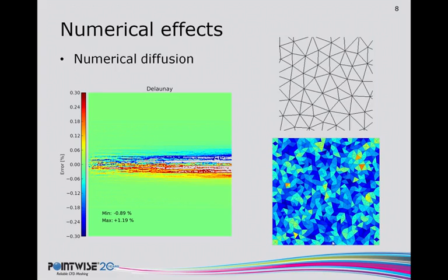Here on the right, this is a heat map showing the skewness of this Delaunay mesh. This is actually a much coarser mesh than the simulation was run on, but this just showcases how you have this random collection and random assortment of skewness. The more red the color, the higher the skewness of the individual cell.